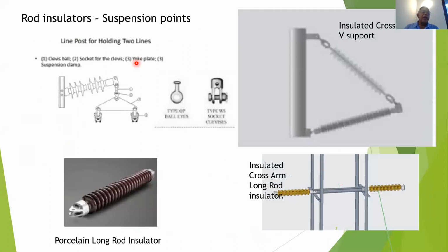Yeah, rod insulator, suspension points, rod insulator. Now, this is the eyeball, what I talked about, and this is the other device. This clevis goes into the pin of the last insulator, and this can be connected over here.